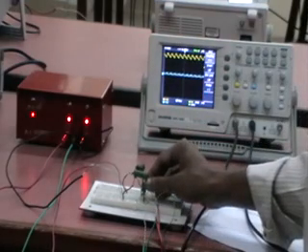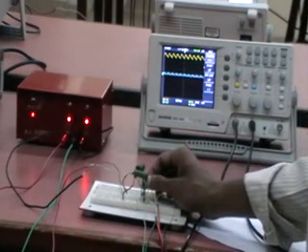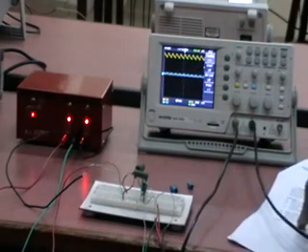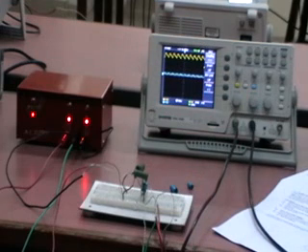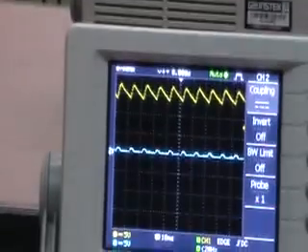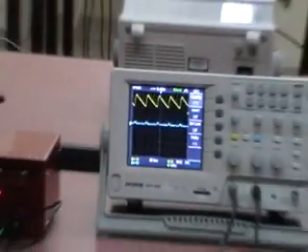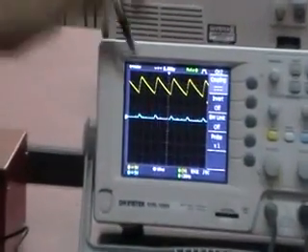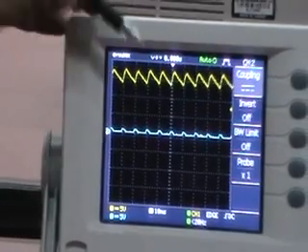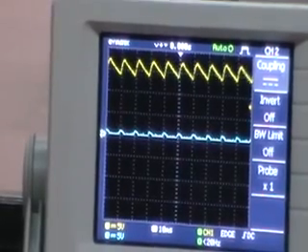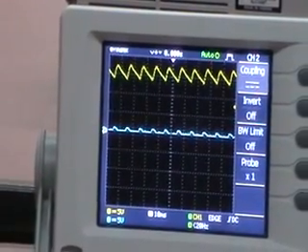The final part that we have to do is to compare the peak to peak ripple voltage and the peak value of the diode current for both half wave and full wave rectification, with the 330 microfarad capacitor. We can compare easily by switching the out of phase button off. This is the half wave rectifier, and you can measure the peak to peak voltage and the diode current. By switching it on, we can find the peak to peak voltage of full wave rectification and the diode current. So we can compare both these voltages and currents, and easily verify which is greater and which is not.